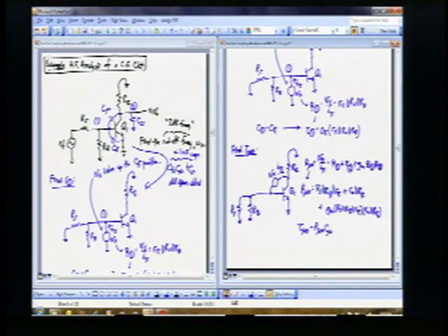Yes? I see the formula sheet says the GM is a capital GM, not the small GM. Yeah, that's right. And so I guess I skipped a few steps here, but see, this is capital GM here, right? Because capital GM is usually equal to GM over 1 plus GM times RE, right? But RE in this case is 0. And so because RE equals 0, GM just equals little gm. Okay? So that's what I did there.